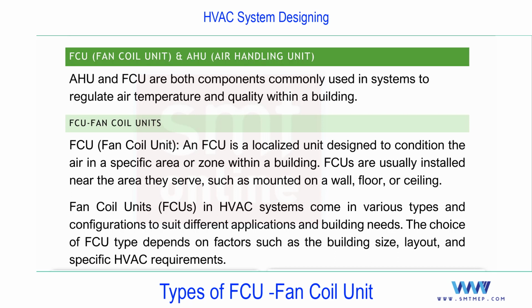You see, this FCU and AHU is an air side unit, and this is common for split. I'm not talking about both, just in general at this level. After learning this, you'll get a clear idea. So if you talk about FCU and AHU, you'll find them in a split system, ductable split, VRF, and the chilled water system. And district cooling system is also a chilled water system, but a chilled water system for a community. Okay, so even for district cooling system, this is applicable. And apart from this, if you talk about geothermal, in that case also you'll find this unit. So this unit is common almost for all the systems.